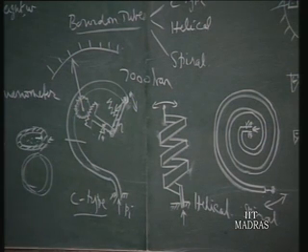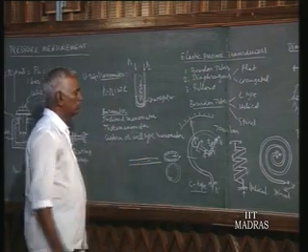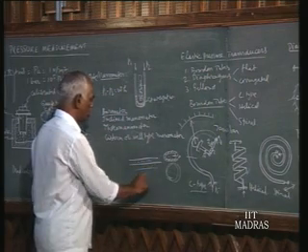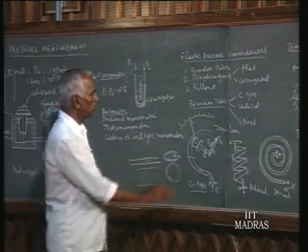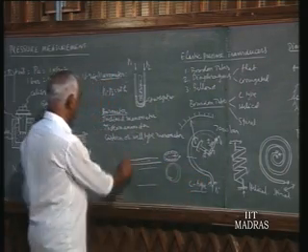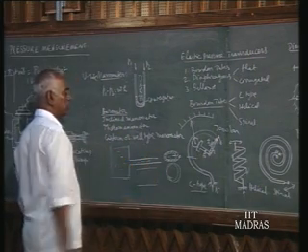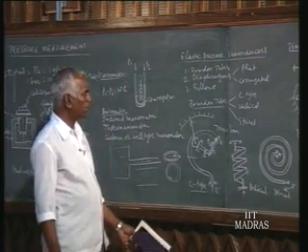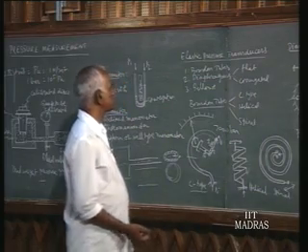But for dynamic pressures, we should be careful with the tube carrying the dynamic pressure, because when a pressure fluid flows through any small piping, that frequency is damped out. So whenever we carry dynamic pressures to an instrument, we should have a sufficiently large cross section so that the pressure variation is truthfully transmitted to the instrument end. Otherwise, the dynamic pressure taking place in this vessel cannot be carried by thin tubing to an instrument, or we have to mount the instrument on the tank or pressure vessel itself. Those are the precautions we have to take.